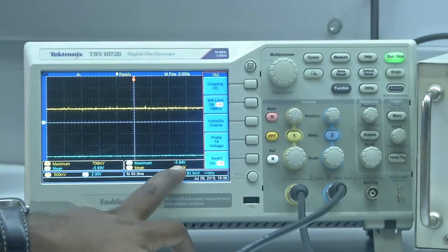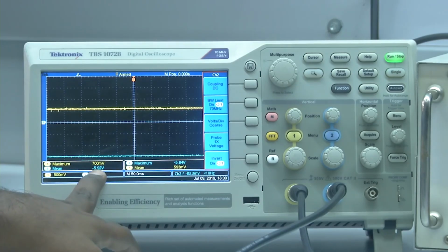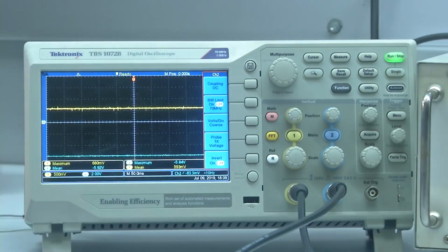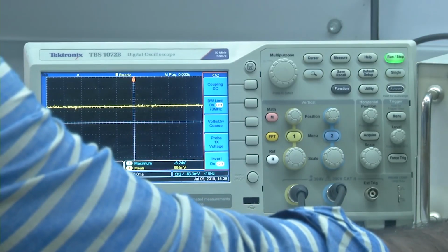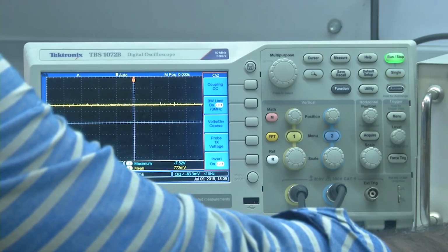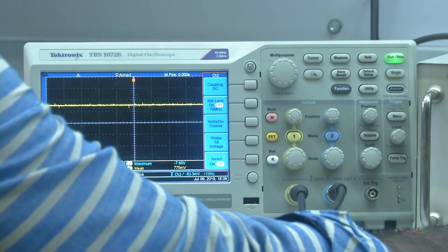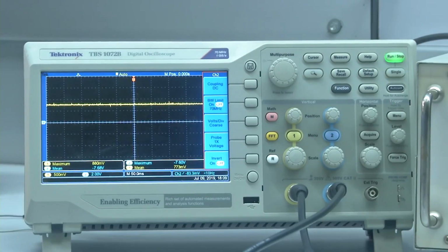So applied input of mean value of 594 milli, we are getting minus 5.92 volt, which is also close to 10, right. So from this it is clear that as we keep on increasing the voltage, let us go with 1 volt, we should get an output of 10, provided we cannot go more than 1.2 or 1.3 volts, because if you go more than that, since the gain is 10, the output voltage will go to 12 to 13 volts. Since the plus VCC and minus VCC of the operational amplifier here is 15, above the saturation voltage, whatever may be the output, it cannot be represented. So the maximum output voltage the op amp can show is only till the saturation. That saturation entirely depends upon the power supplies being provided for operational amplifiers.